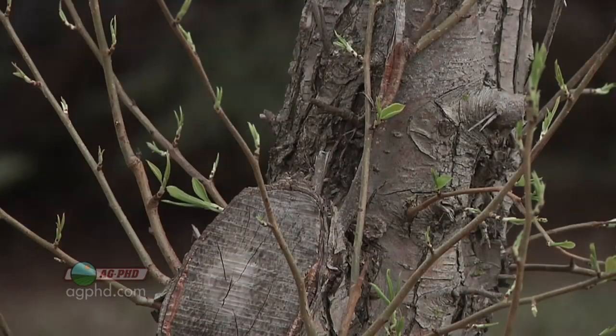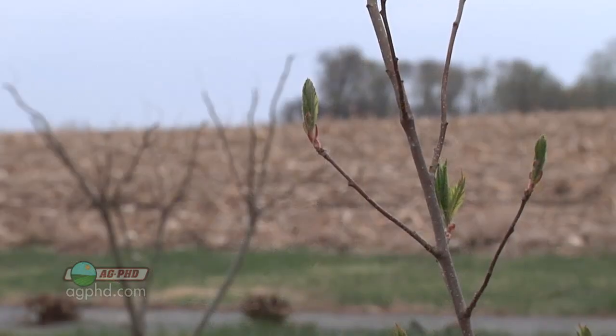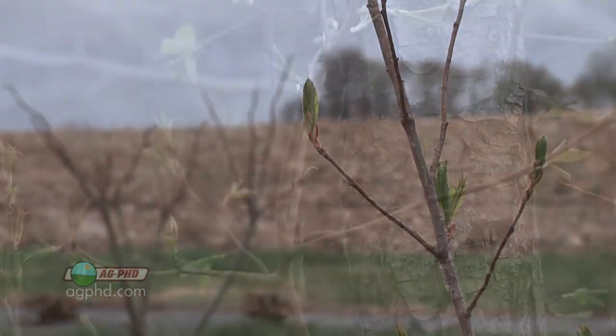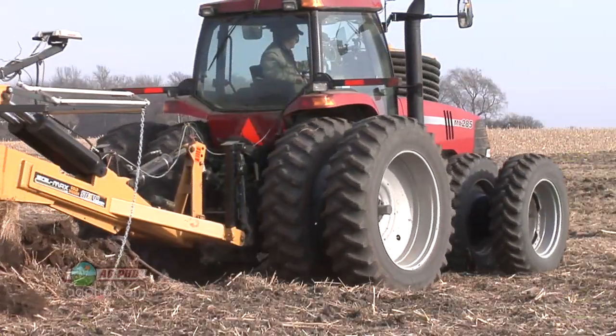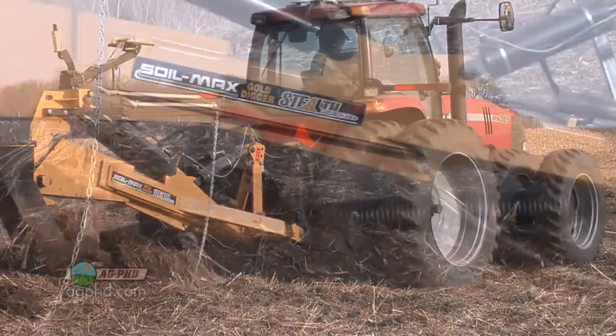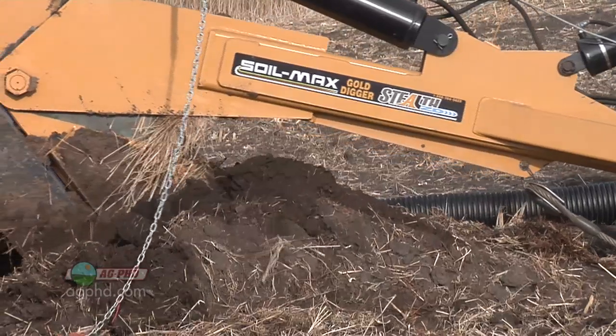And carrying the soil. Additional things that have been done over the years is putting trees, in a lot of cases mini trees, every 40 acres or 80 acres, something like that, to slow the wind down. On our farm, we've done a lot of tiling. That dramatically reduces erosion, and the reason why is because what happens in soil is if there's too much water, the water table gets real high near the surface of the soil.